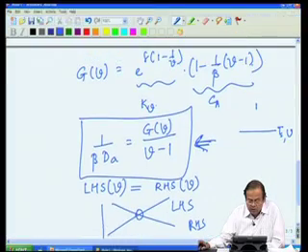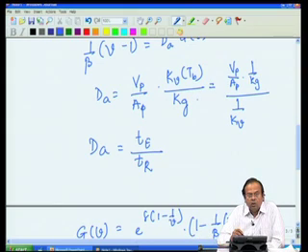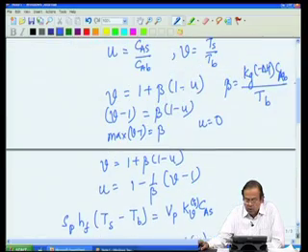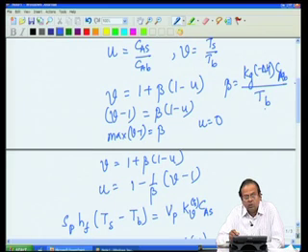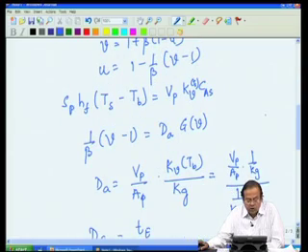If you look at this Damkohler number definition over here, Damkohler number depends on temperature, k_v of T_b. So, bulk temperature will influence Damkohler number. What about beta? Beta also is influenced by the bulk temperature. So, changing bulk temperature is equivalent to changing 1 over beta into Damkohler number.